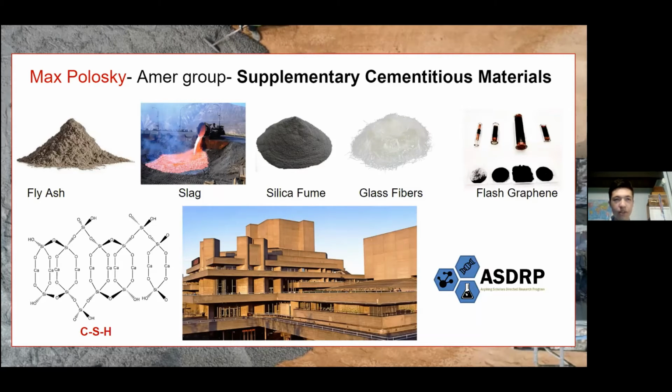Pozzolanic materials are materials that take the weaker product of cementitious reactions, CH, and convert them into the stronger compound, CSH, which gives concrete its strength. So with these in mind, I will talk about some common industry supplementary cementitious materials currently.